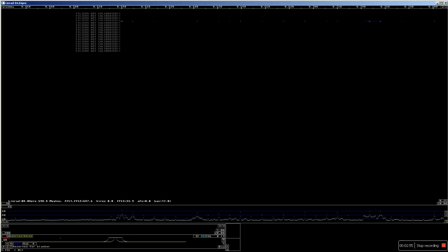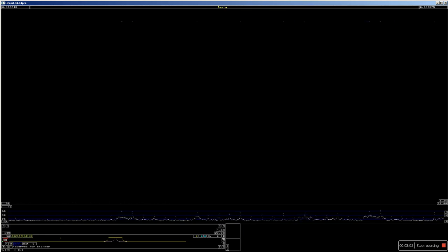And then I want the entire medium wave on the display. So I click here and say I want the frequency range 0 up to, let's say, 2 megahertz. And Linrad finds out I cannot get quite as much, but this is what I can get.